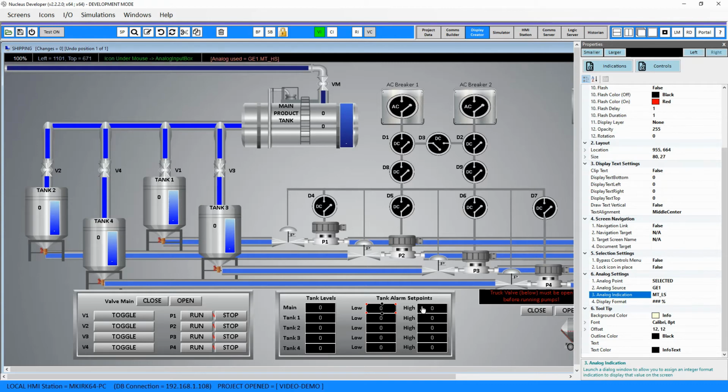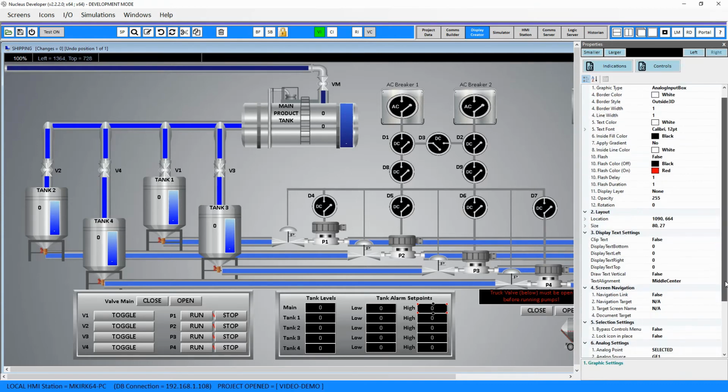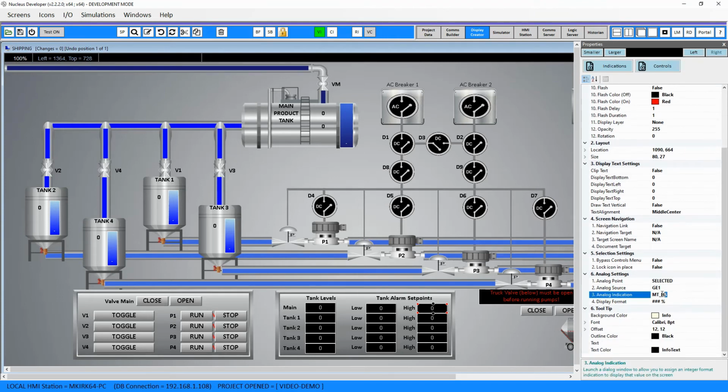So you can use this option only if the PLC is set up to stick to a value in a single register. This is typical in Modbus protocols. Or you would use this method if the logic in the PLC echoes back an indication that was set by the control value it received.